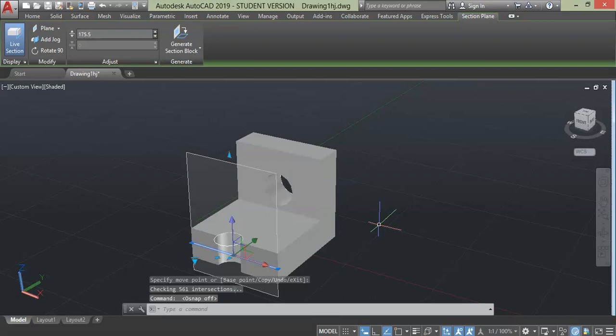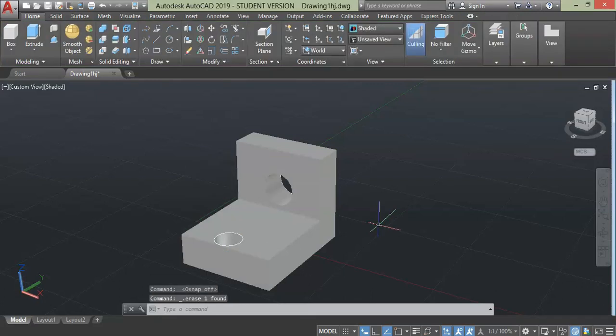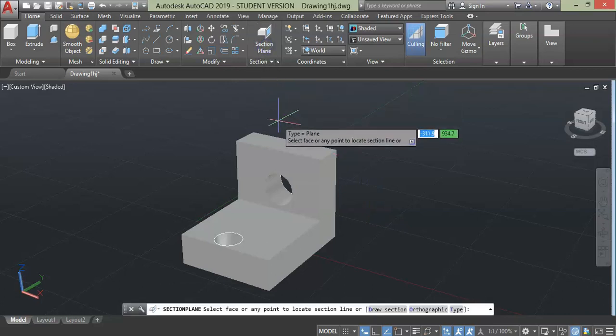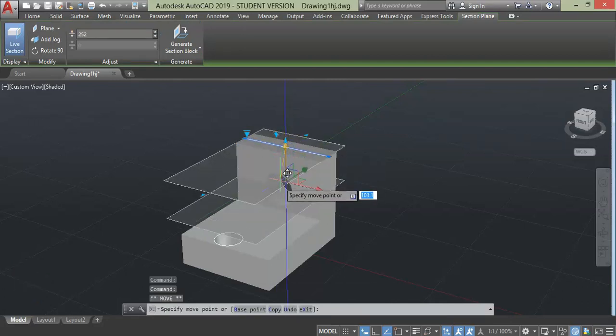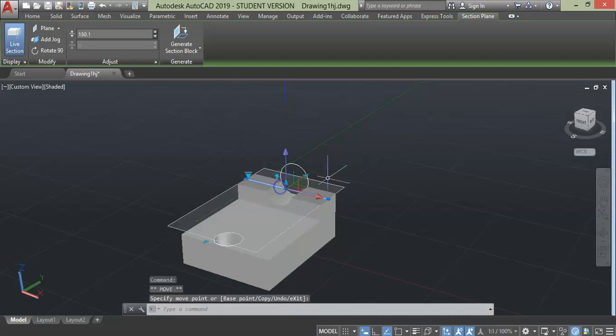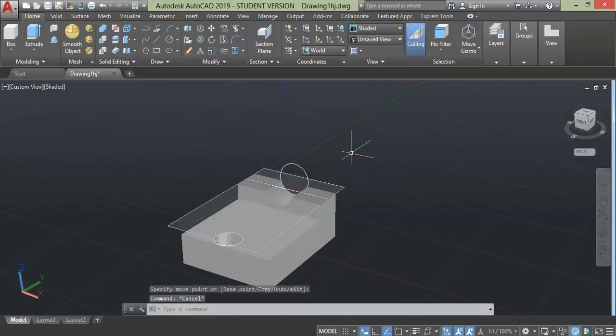The same way, you can apply this command in any part of this geometry. Press the Delete key to go back to the original shape. Let's apply a cutaway to the top. Again, select the plane using the arrowhead. Drag it downward to your required length. Press Escape. Now you will be able to see the section view.